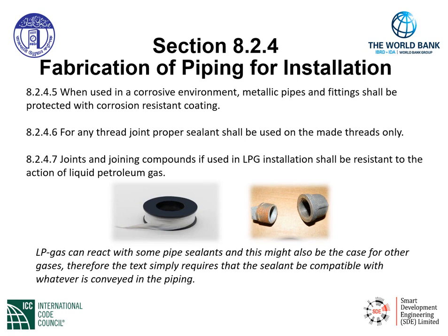8.2.4.7, joints and joining compounds, if used in LPG installations, shall be resistant to the action of liquid petroleum gas. Now, certain compounds may react with LPG.